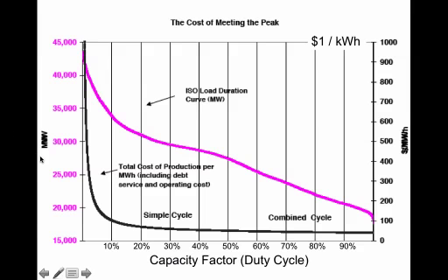This graph correlates the demand in megawatts to the capacity factor and the cost. We see here that this is 20,000 megawatts, or 20 gigawatts. So at less than 18 gigawatts, we need that all the time. However, something like 30 gigawatts, we need that only about 20% of the time. And if we look at this curve, this correlates that capacity factor with the cost of electricity.